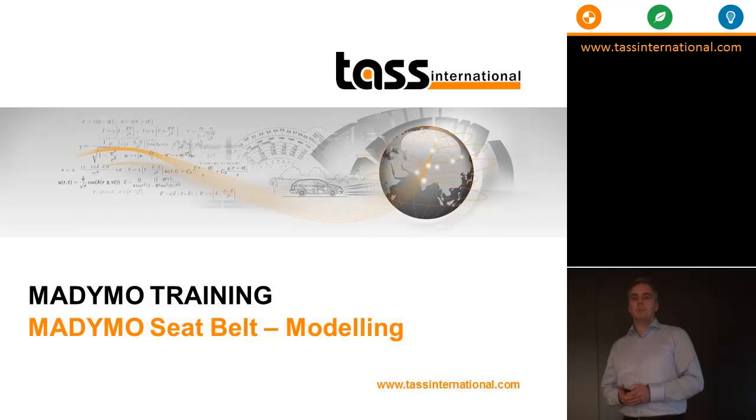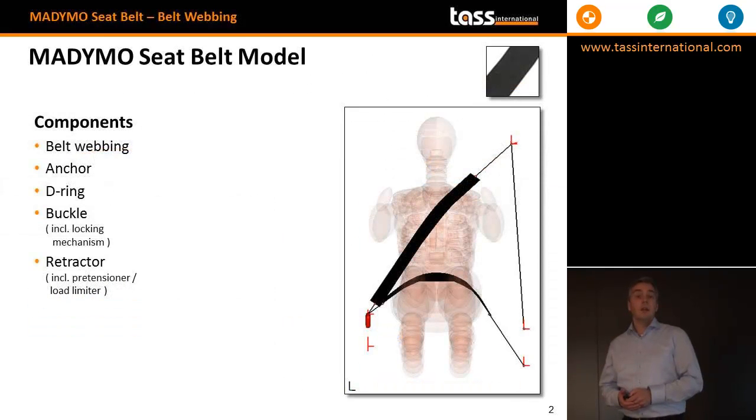Next we will discuss the belt triggering conditions. In the real world you have sensors, control and actuators for a belt system. So the sensors are often sensors that detect vehicle acceleration and threshold levels for that, as well as webbing pull-out rate. Control is normally done with control algorithms inside a restraint system ECU, and the actuators you can consider the spool locking, the pretensioner firing, or triggers for the webbing grabber or the load limiter.